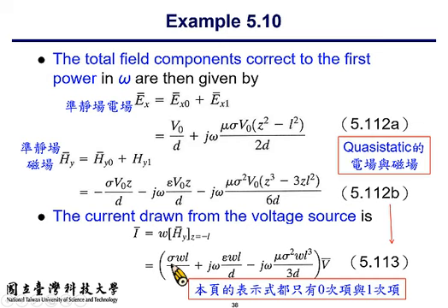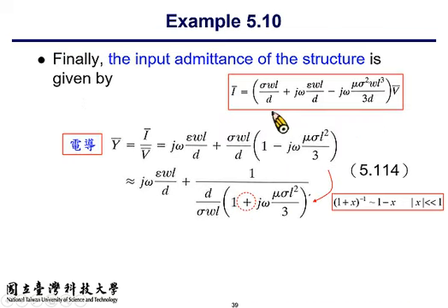And we can also identify the three terms here can be substituted with per unit length equivalent capacitance and equivalent inductance, as well as equivalent conductance. So they can be identified as a combination of this. So here, this is the capacitance, this is the inductance, and this can be substituted with the resistance.